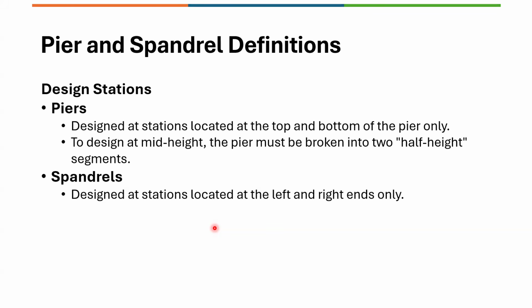And spandrels, it is going to provide output only at two locations again, on the left and the right, the coupling beams. So in case you want the variation of the forces to be captured along the length of the spandrel, then you'll have to mesh the wall elements modeled for the spandrel and then label them differently to capture this variation.